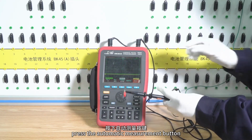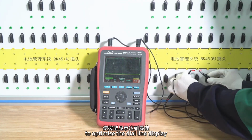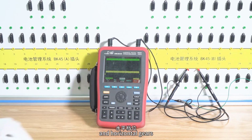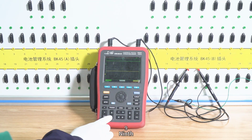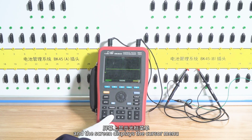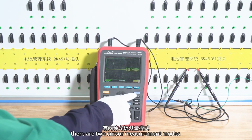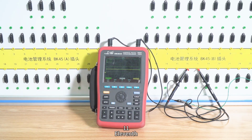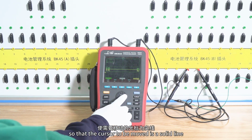Seventh, press the automatic measurement button. Eighth, the digital oscilloscope will be automatically set to optimize the waveform display. On this basis, it is possible to further adjust the vertical and horizontal gears until the waveform display meets the requirements. Ninth, press the cursor measurement button and the screen displays the cursor menu. 10th, press the F1 button. Open the cursor. There are 2 cursor measurement modes in the cursor menu, voltage and time. 11th, we measure the voltage value this time by using the F2 button on the panel, so that the cursor to be moved is a solid line.